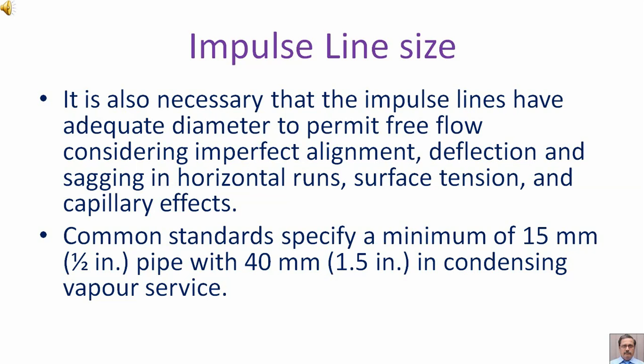Common standards specify a minimum of 15 mm, that is half-inch pipe, with 40 mm, that is 1.5 inch, in condensing vapor service.